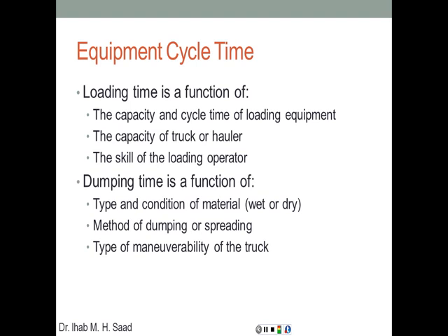The dumping time is affected by the type and condition of the material, how easily it is going to flow from the bed or from the bucket of that equipment, whether that material is going to be wet or dry, the method of dumping or spreading, whether it's going to be end dump or bottom dump, or whether you're going to be dumping into a pile or spreading it around, and the type and maneuverability of the truck or the piece of equipment, basically.